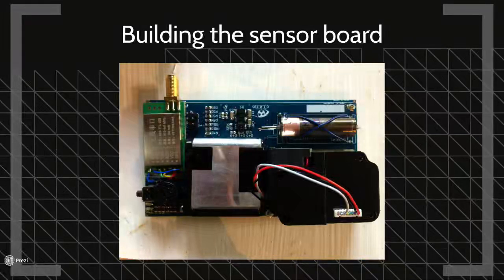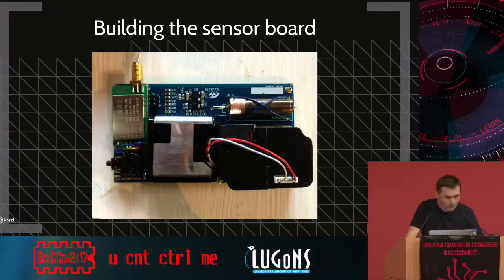Now for the sensors part. Again, it was an issue of time, so I had to try to somehow reuse something of my previous work in order to get this done as quick as possible. So what I did was to go for one of the PCBs which were for one of the portable URAD monitor units. It was nice because it already had the battery, it already had the DC to DC converters to handle the battery. It already had one for 3.3 volts and one for 5 volts.